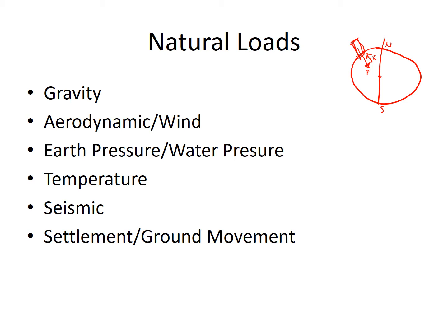But there are other loads other than just the weight, and again they all have to find their way through a load path, and they may come down, and again this reaction has to increase to match the combination of all the loads from gravity and other sources. So other sources might be aerodynamic forces on the structure. So if, for example, we have a portal frame building with walls and roof,